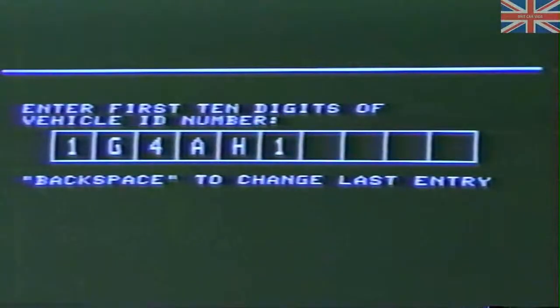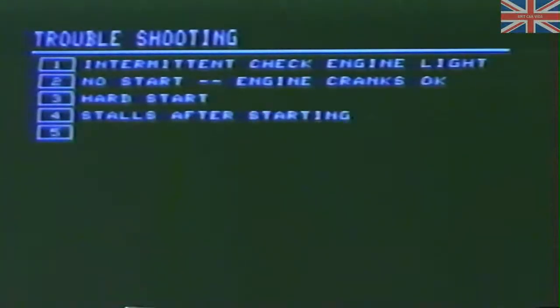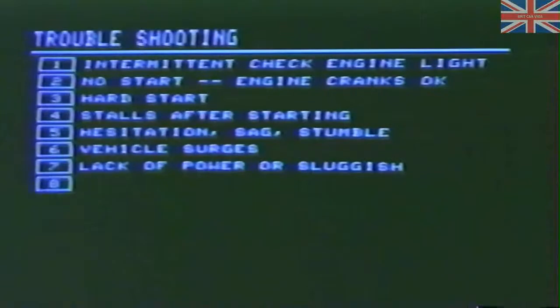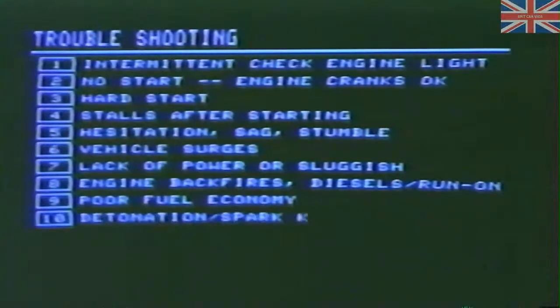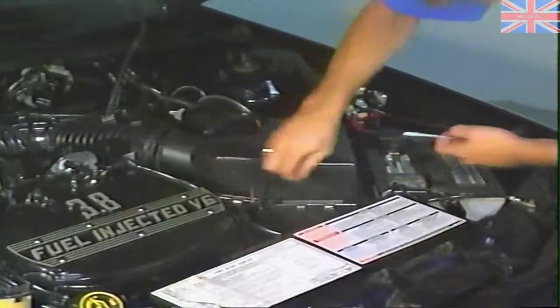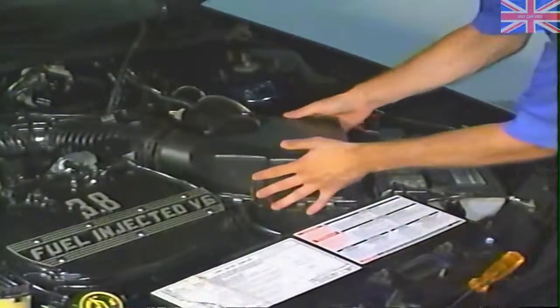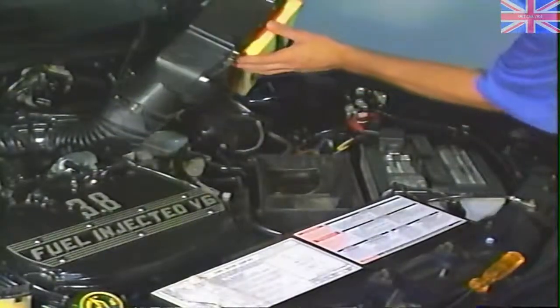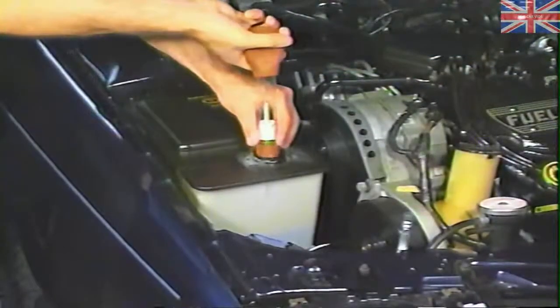The first step to a successful repair is to derive some general information, particularly the VIN code and the exact details of the complaint. Always ask the customer the questions necessary to determine exactly what the complaints are and when they occur. Remember, you cannot diagnose a problem that does not exist. Next, do a complete visual inspection, checking the spark plug wires, the air filter, battery terminals and voltage, the output of the charging system, and the coolant and antifreeze level.